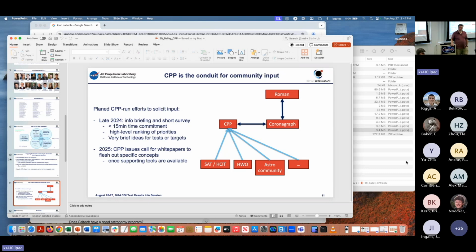The LOFS line of sight loop is orders of magnitude faster than Roman's reaction wheels can possibly move the observatory. And our FSM is effectively a zero exported force mechanism. It's like the most beautiful thing we've ever made. So I would say we'll recover almost instantaneously from a slew. Once we've done our acquisition process, there'll be very little ring down happening after that. At least talking about the observatory, not thermal aspects. Thermal, yeah, which are 10 minutes.